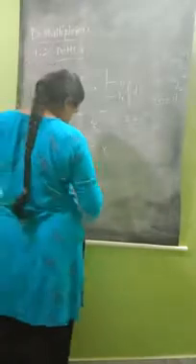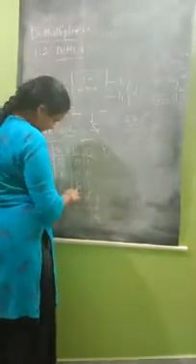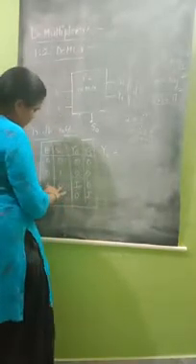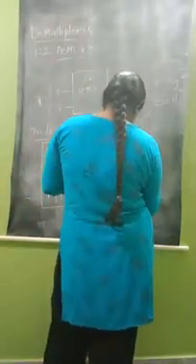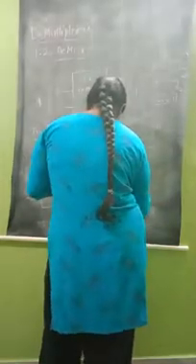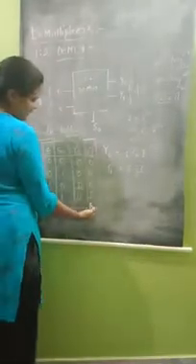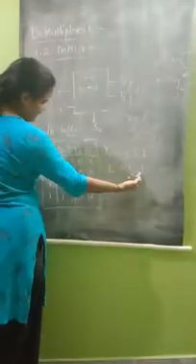So Y0 is equal to, here the output is enabled and the inputs are enable 1 and S0 0. So that is E and S0 bar and I. And Y1 equals E, S0 and I. Here the output is enabled, so 1 1 1 means E and S0 and I.